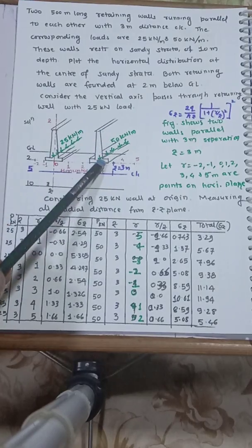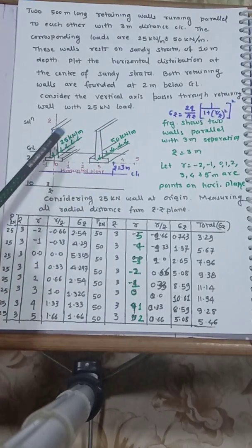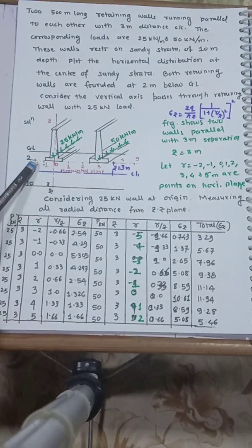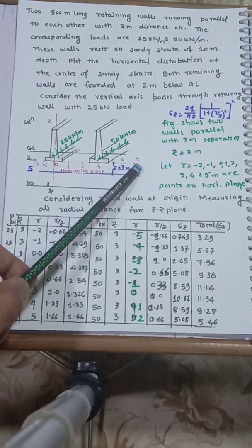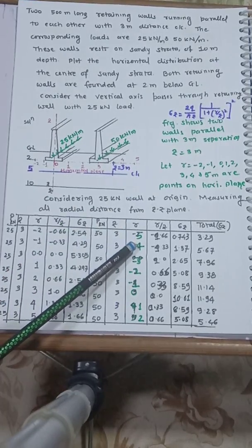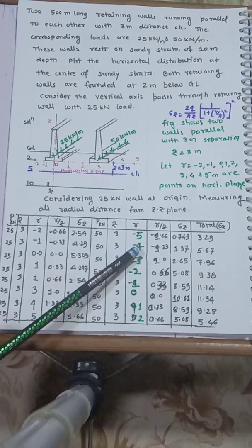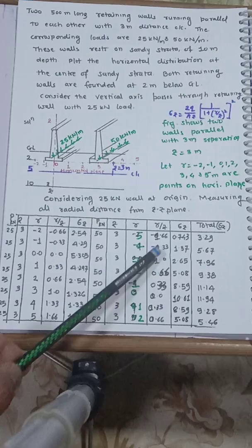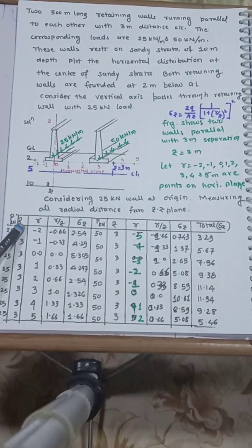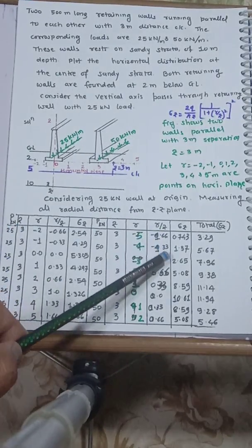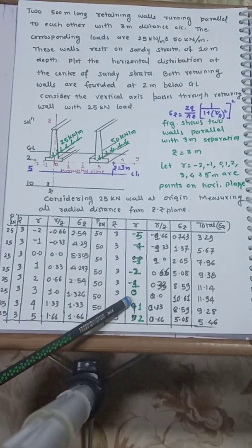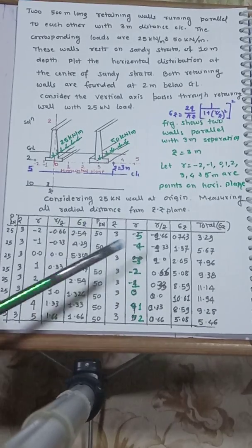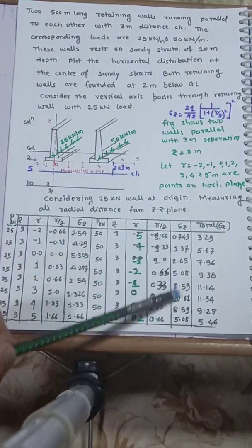Now considering the second wall and neglecting the first wall, considering this as 0, -1, -2, -3, -4, -5, and right hand side it is 1, 2. So you can see here maximum is -5, -4, -3, -2, -1, 0, 1 and 2. So find out their R by Z. Z I put it here the same column, 3 meter. So R by Z up to 0, left hand side of the wall all are negative and right hand side of wall are positive. So substituting this equation you can find out sigma Z.